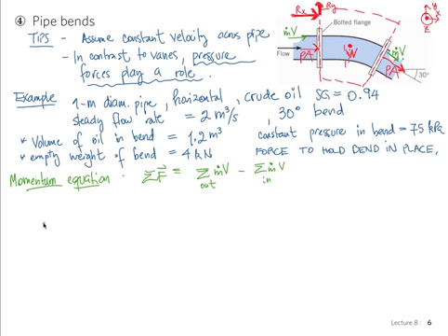So we can actually pretty much write all the forces now. The sum of forces is, again, the weight of the pipe plus oil inside, which points in the negative z direction, and all the pressures and the reactions. And so we have sum of forces as a vector is equal to, let's look at the x direction first. The x direction we've drawn the reaction in the positive x direction, so plus Rx, with P times A also pointing in the same direction, plus PA, pressure times area. And we have a component of